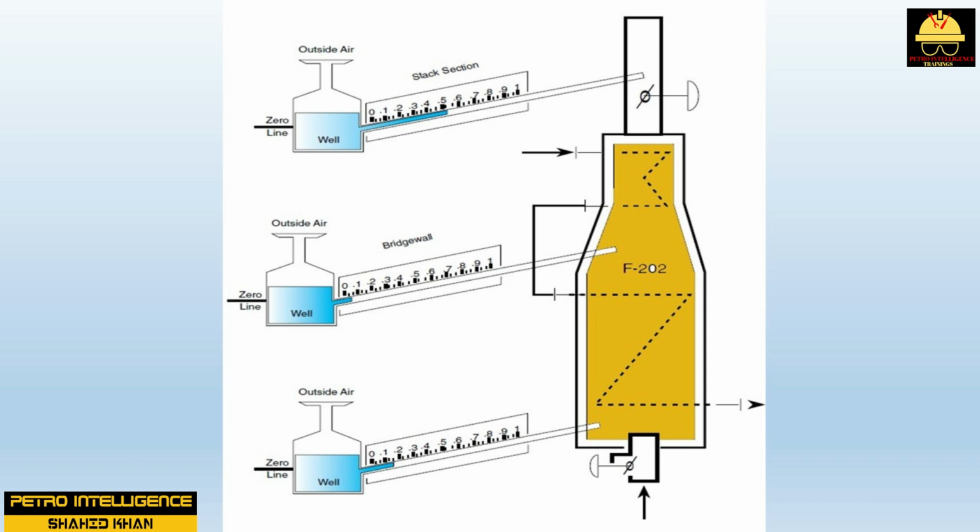Some dampers resemble huge butterfly valves and require only 1/4 turn to be 100% open or closed. Other dampers resemble ordinary window blinds. Any rise in furnace pressure keeps secondary and primary air out of the furnace. The damper can be positioned to increase or decrease airflow. The different drafts or pressures found in a furnace. These readings are given by an inclined furnace tube gauge.